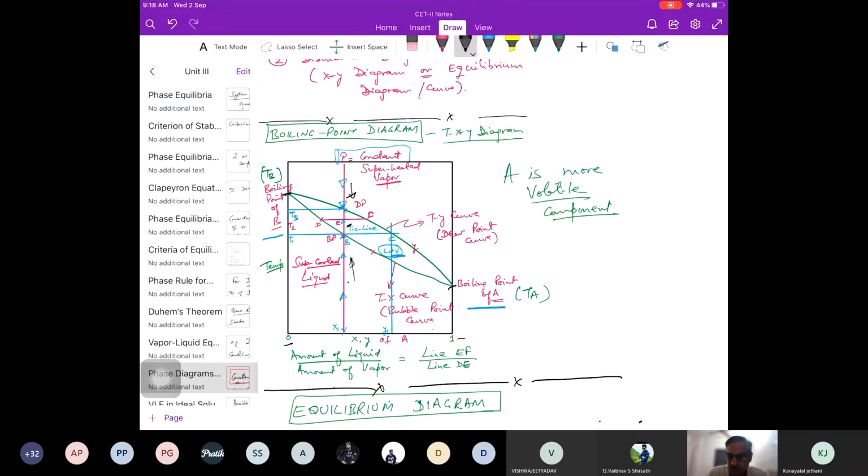जब कंडेंसेशन होता है, वेपर लेके हम कंडेंस करते हैं, हीट एक्सचेंजर डिज़ाइन करेंगे आप, तो it is always condensing between dew point and bubble point. वो रेंज में पूरा कंडेंस होगा. और जब बॉयल करेंगे कोई लिक्विड, when you boil liquid और सॉल्यूशन, it will evaporate and form vapor between bubble point and dew point. So understand the difference between bubble point and dew point. There is no boiling point of a solution.